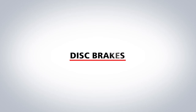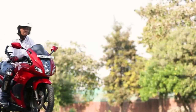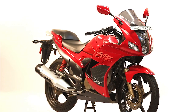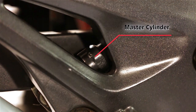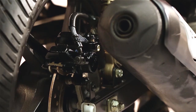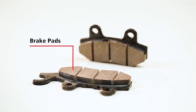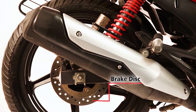Next, let us look at the disc brake. Disc brake consists of the following parts. These are master cylinders, which convert brake lever or brake pedal operating force to hydraulic pressure. These are brake calipers, which work by hydraulic pressure from the master cylinders. The brake pads are made up of frictional material and are installed in the brake calipers. The brake disc rotates together with the wheel.